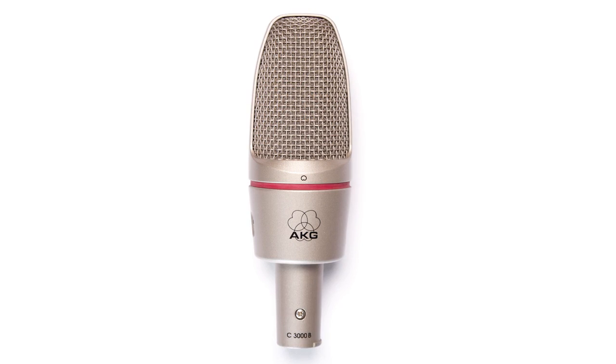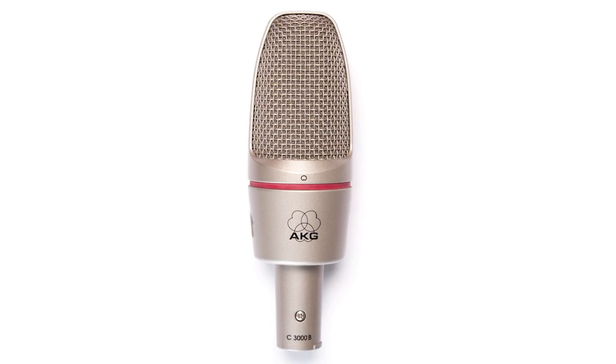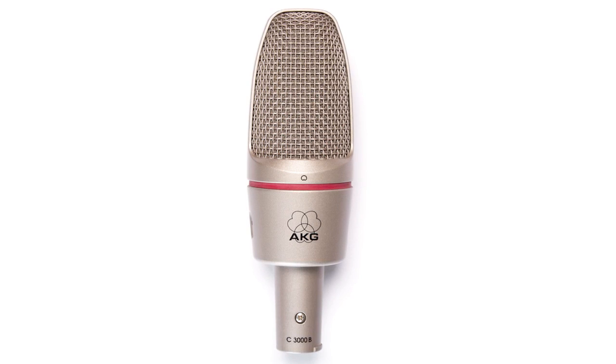If you're not familiar with microphones, you might be wondering what the difference is between a large diaphragm condenser and a small diaphragm condenser. Essentially, it comes down to how the mass of the microphone element affects the frequency response of the microphone. Because a large diaphragm is larger, it can have a higher signal output, a lower frequency response, and sound beefier when you are trying to take advantage of proximity effect.